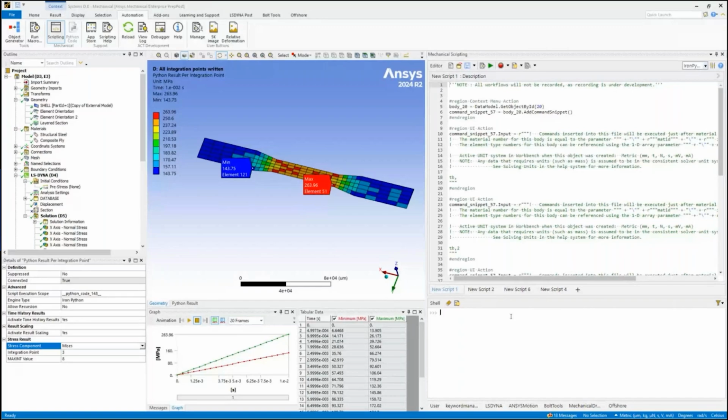But really, how do we access that data model? Everything within Python is an object. It's an object-oriented language in many respects. And so what we need to do is generate a Python object, or use Python objects to talk to the model within our Ansys Mechanical. And we can do that quite simply.